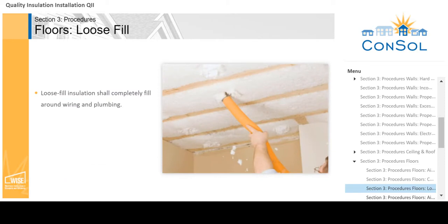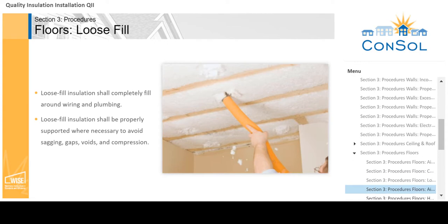Loose fill insulation shall completely fill around wiring and plumbing and be properly supported where necessary to avoid sagging, gaps, voids, and compression.